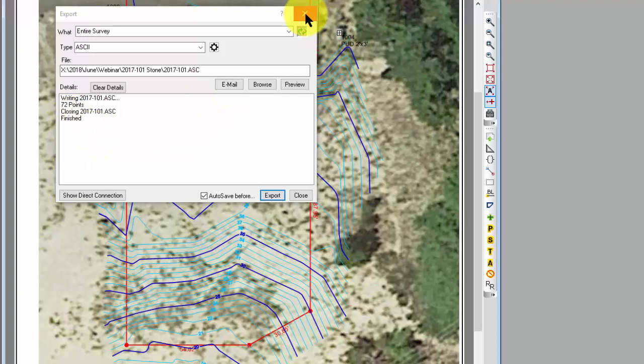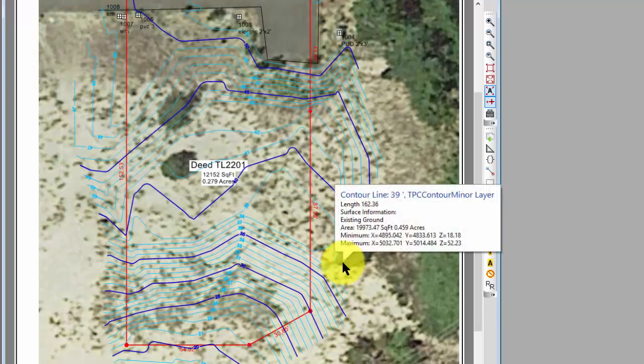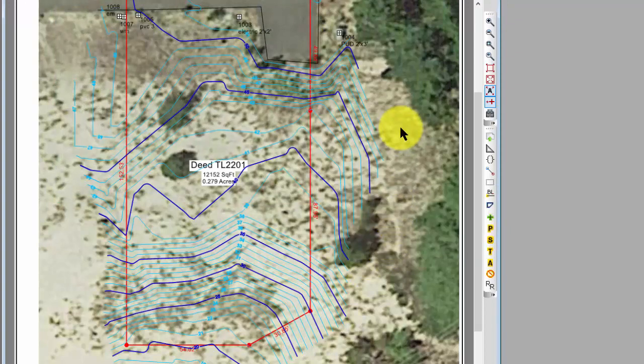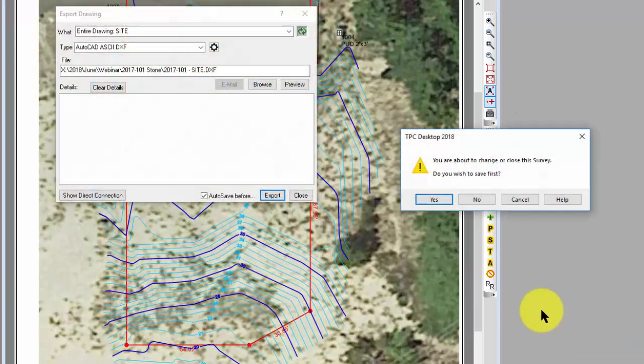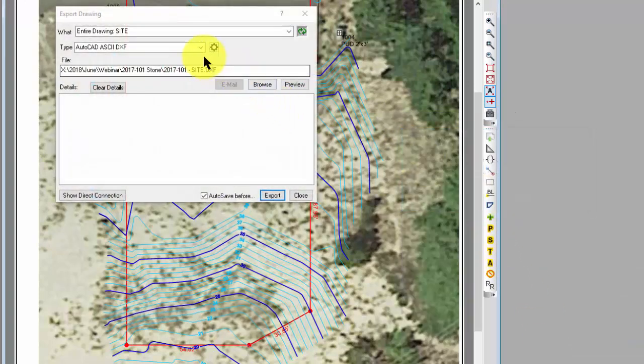So the architect now has everything. Primarily interested in the utilities, any vegetative features like trees and stuff he has to work around, and then he's got all of my topo points as well. And then the final thing I did was I went ahead and sent this out to DWG files. Let's go ahead and export this. We're going to choose AutoCAD DWG.